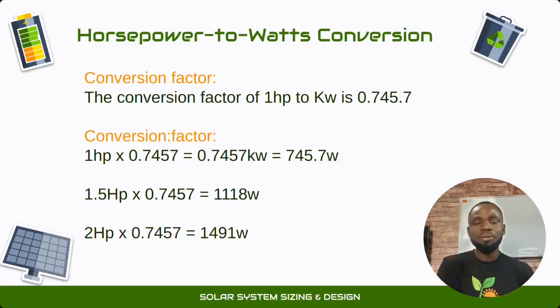Remember what I said, the most important information we need from this energy audit is our total load and our total daily energy consumption. We need these 2 important pieces of information; we are going to use them to size other components of the system.